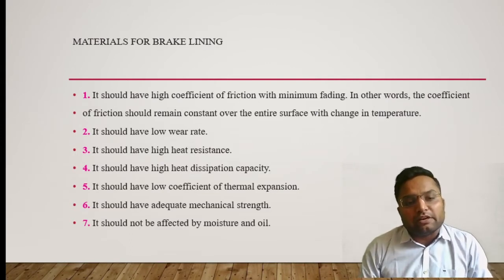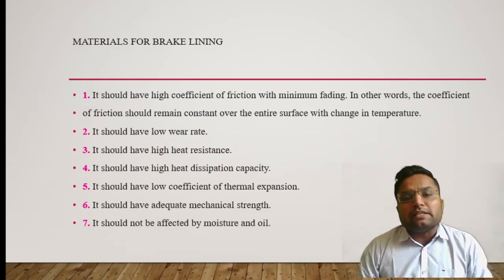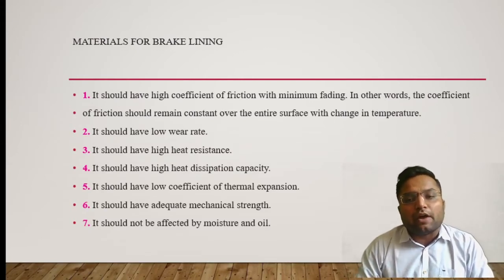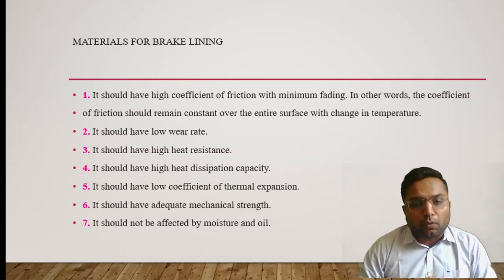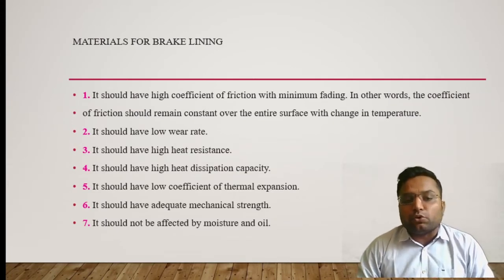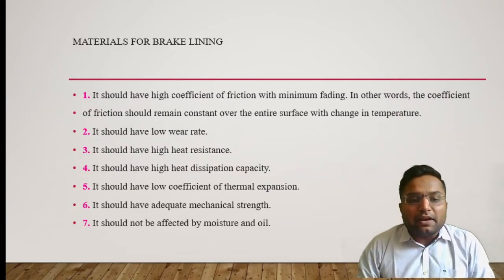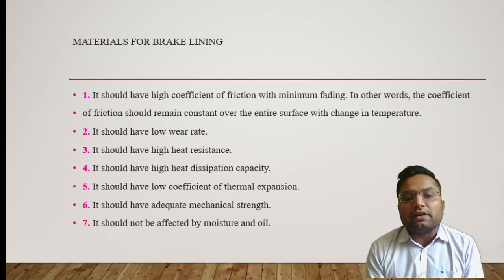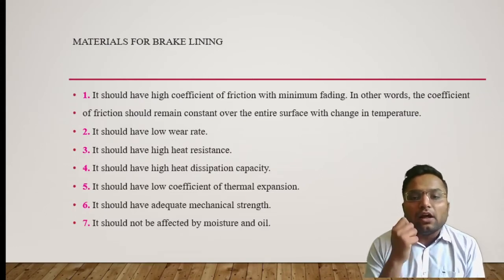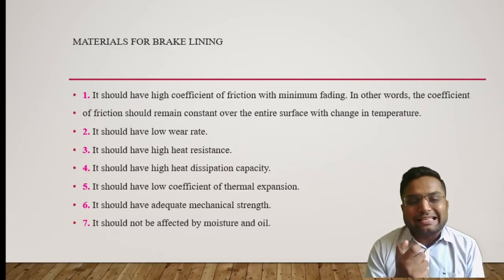And how will it break the torque of the rotating element? By means of friction. So our material should have high friction with minimum fading. It should provide high friction between that rotating element and our element which is stopping our moving element, with a lesser amount of fading.